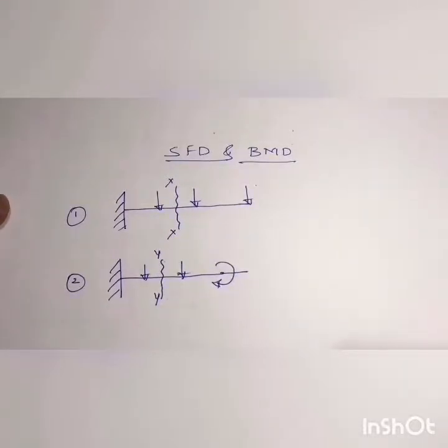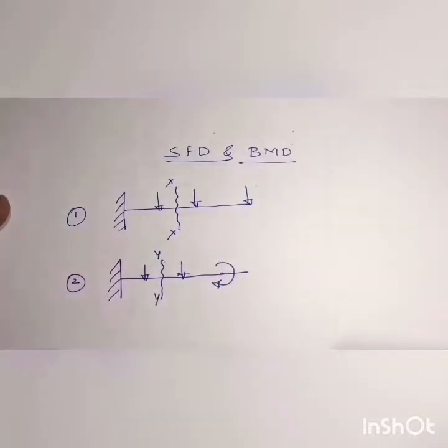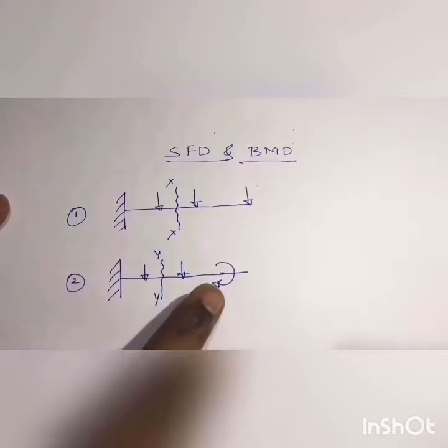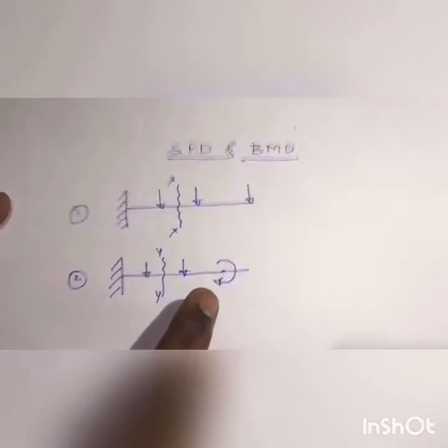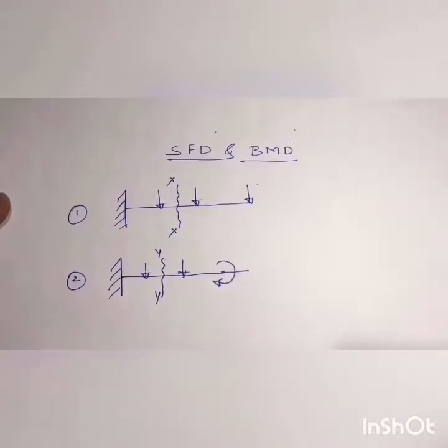Let us come to bending moment and the bending moment diagram now. Consider figure 2, which also is a cantilever, and here let it be subjected to some point loads as well as some moment. Let YY be the section of interest now. Bending moment at this section of interest, YY, is defined as the algebraic sum of all the bending moments due to forces and moments acting either towards the left side or right side of this section of interest.